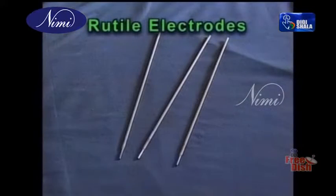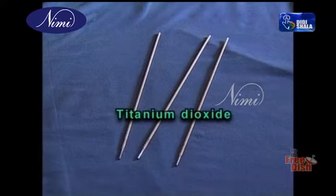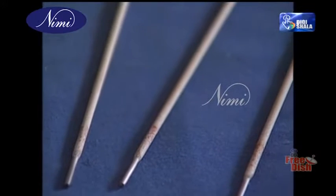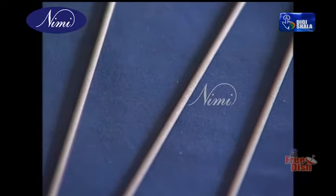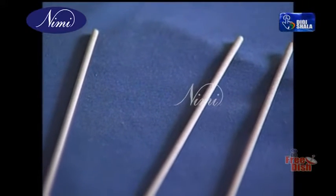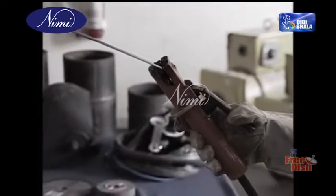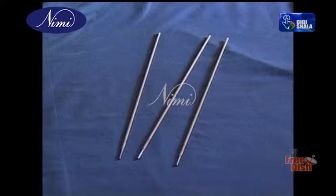Rutile electrodes are general-purpose electrodes having coatings based on titanium dioxide. These electrodes are widely used in the fabrication industry as they produce acceptable weld shape and the slag on deposited welds is easily removed. Strength of deposited welds is acceptable for most low-carbon steels, and the majority of the electrodes in this group are suitable for use in all positions.